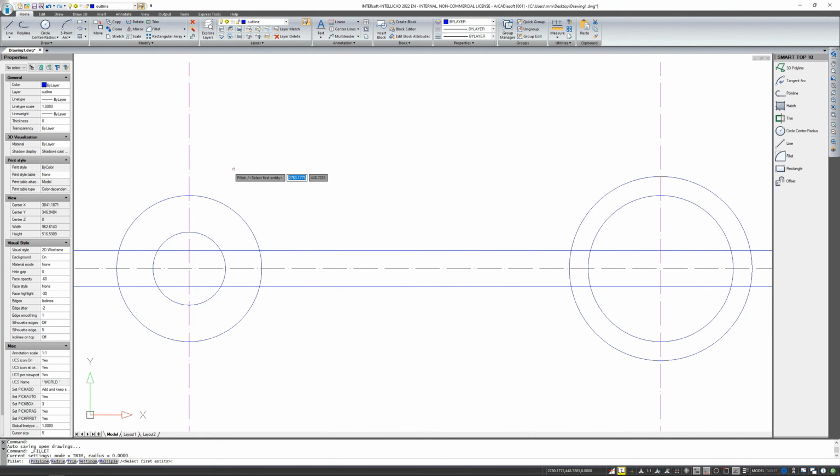Sometimes I select an element under the right button, select its modification, and sometimes I enable the option to modify first and then select the element. It doesn't really matter what you choose first, whether we select an element and then choose the modification option or vice versa. I will show it interchangeably here. When I round something off, I turn on the Fillet option first and then show the element. But mostly I select the element first and then I choose the modification option with the right mouse button.